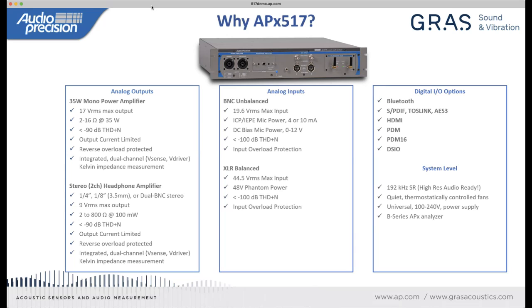The other thing we'll be taking advantage of is we need to get a signal back from a reference microphone, a measurement microphone, and we'll be using an unbalanced measurement microphone that requires constant current power. So we'll be taking advantage of the fact that that is also built into the 517.